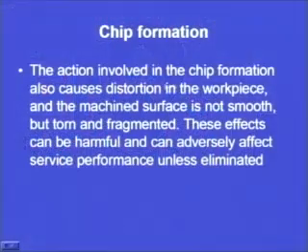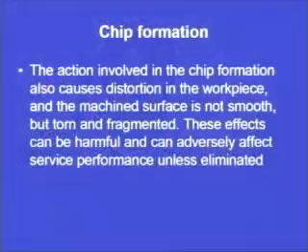The action involved in the chip formation also causes distortion in the workpiece. Now the workpiece may also get distorted and the machined surface is not smooth. Already I have told the smooth surface finish may not be achieved, but torn and fragmented. The surface will be torn and fragmented. These effects can be harmful and can adversely affect the service performance until eliminated.